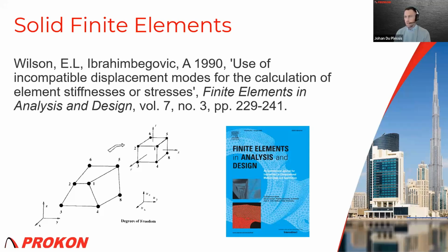But I think what you must just know here is that your compatible displacement field finite elements give you what's called a lower bound solution, whereas these incompatible displacement field models that we've added here are, in our opinion, better for structural and civil engineers, because they give you a lot more reliable results in terms of stresses and strains in the model. So definitely keep a lookout for that.